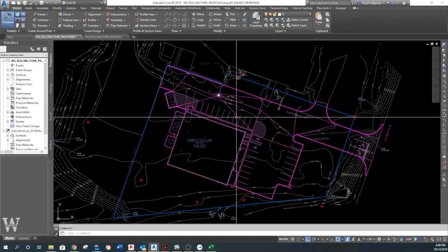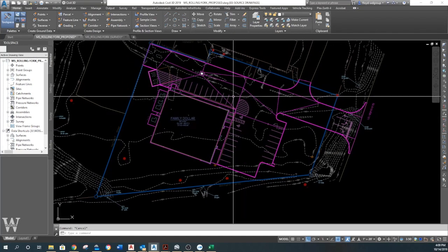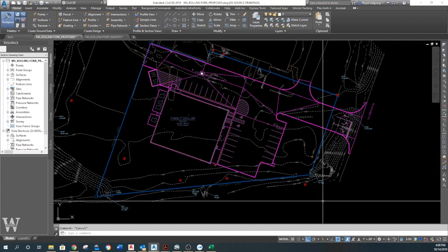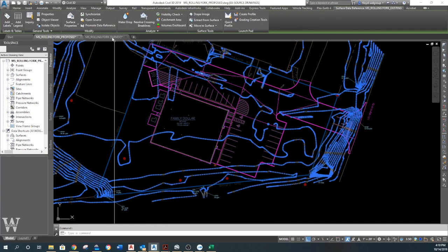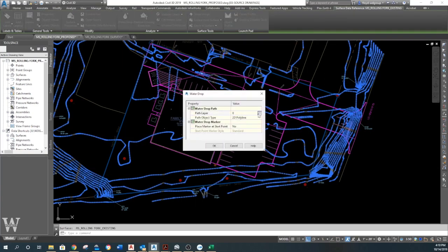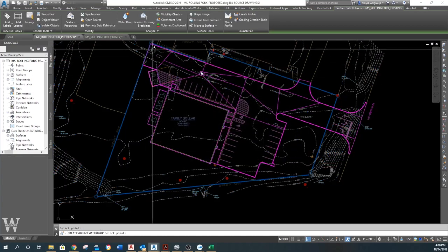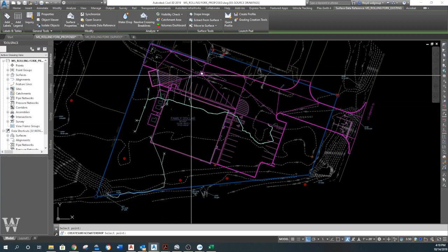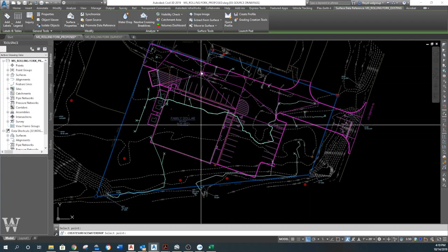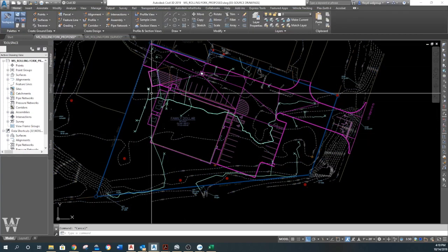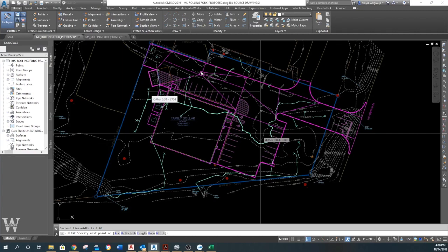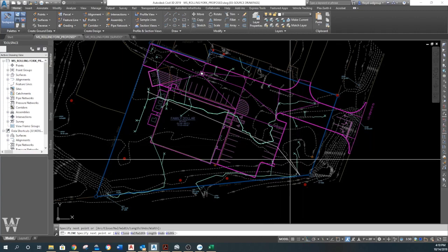All right, so close this. Time of concentration is the farthest point that water has to travel to get to discharge at the site. So we can do this with our water drop. We click right here, click us a path, just cause water drop. We can start right here and see that water goes that way, just to see where existing water on this site goes. So really what's happening is it's probably coming right here to right there. This right here would probably be the travel path for my time of concentration.